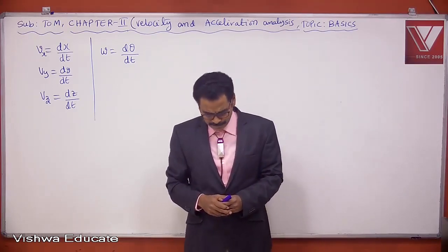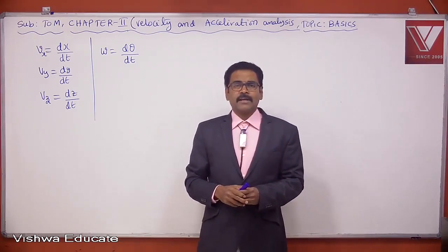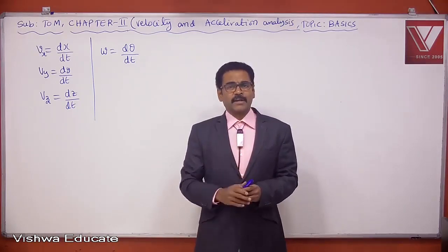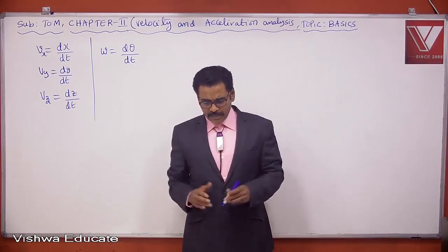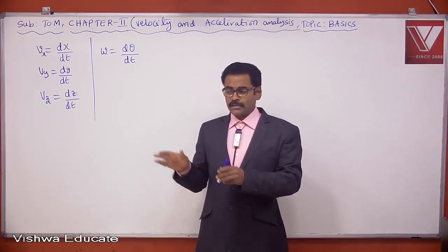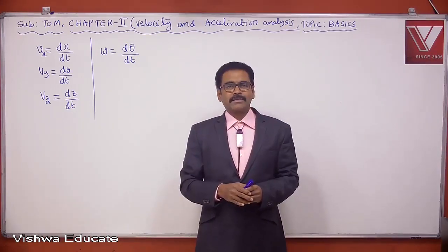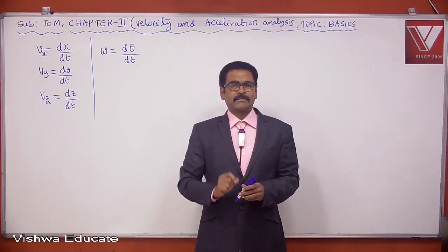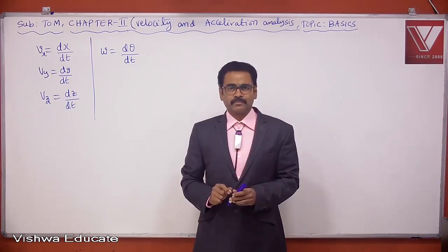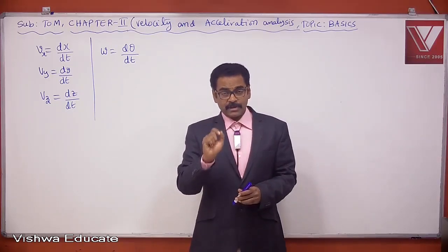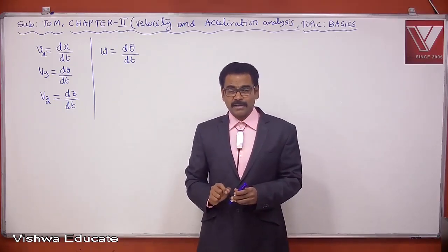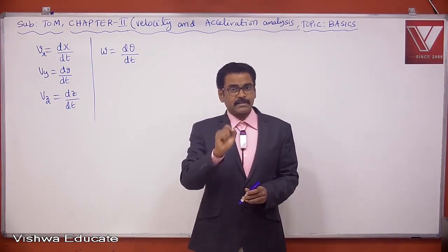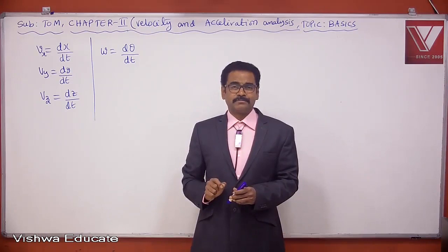For instance, I am going to design a new mechanism. So currently it is not existing. I am designing it now. For a new mechanism which is in the design stage, velocity analysis means fixing of velocities of various links of the mechanism, or fixing of velocities of various strategic points of the mechanism.